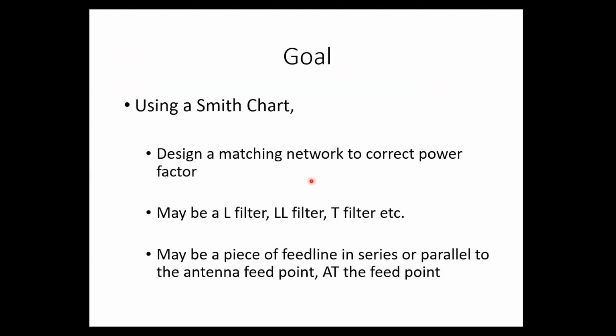All right, so here's our goal. Using a Smith chart, we want to design a matching network to correct the power factor. It can be an L filter, a double L filter, a T filter, whatever. Might just be a long or maybe not so long piece of coax.